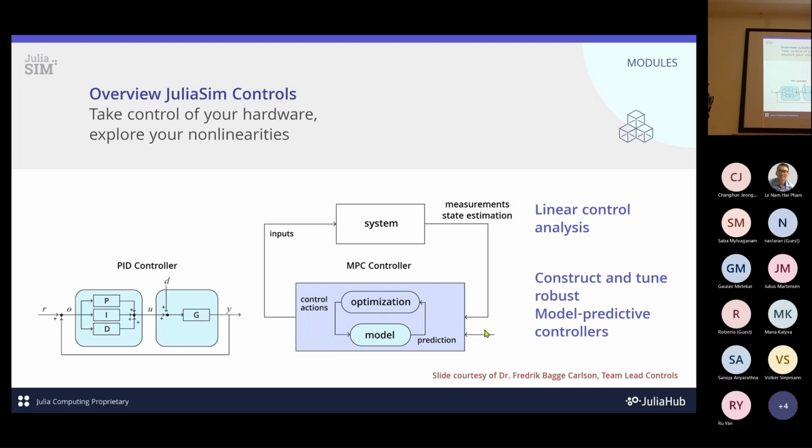So this first component is this prediction model, and then we'll have a set of control inputs that are sent to the real plant. And then from the real plant, we'll have a set of measurements from which we'll have a state estimator, an observer, usually some kind of Kalman filter. And from the state estimation, we return to the prediction model for the next time step.